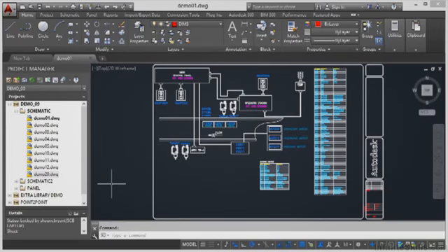You can change the order of your drawings in your Project Manager in AutoCAD Electrical at any time. So for working files purposes, we're still in the project Demo 09, and right now I've got the Demo 01 drawing open here in the drawing area. Now Demo 01 doesn't have to be at the top of that drawing list in the Project Manager. I can select it, I can drag it down this way like so, and I might want it there. If I do that, it puts it after drawing 10. Still the current drawing, because obviously it's highlighted in bold like so, but you can actually just drag and drop.